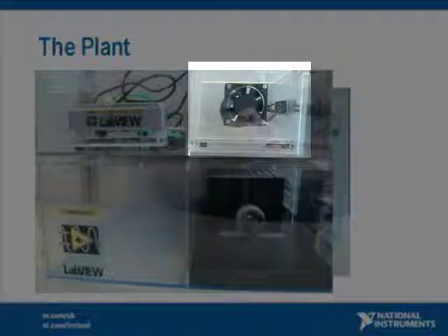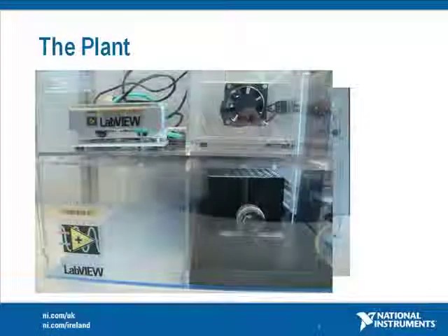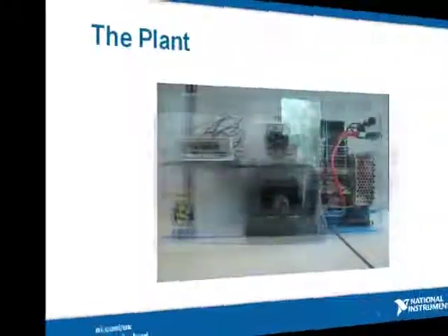We use the scan mode with a digital I/O module to send PWM signals to our temperature controlled furnace. A light bulb would increase the temperature of the furnace and a fan was used to decrease the temperature. Closing the loop on this control was a thermocouple input. The outputs were all set using a tuned PID algorithm.